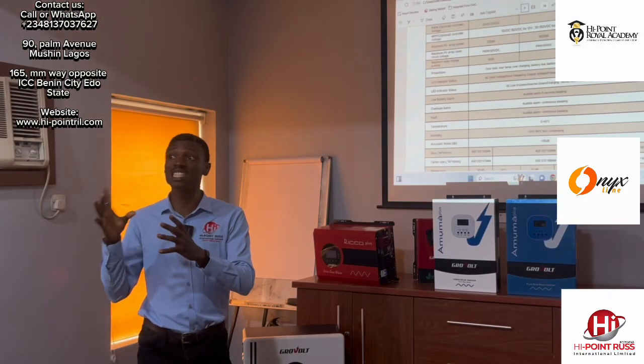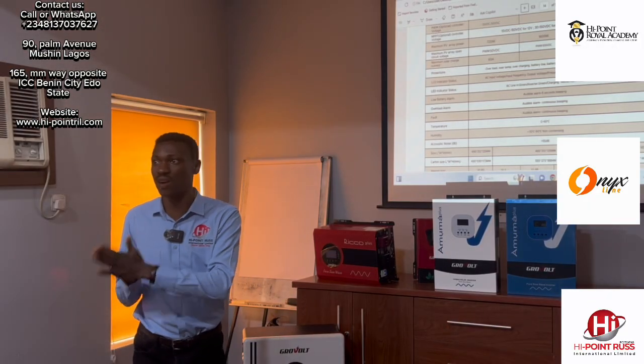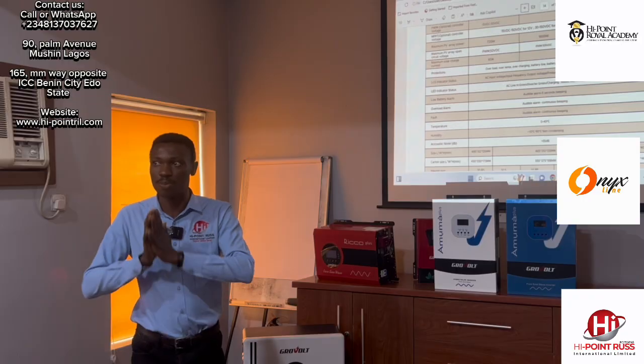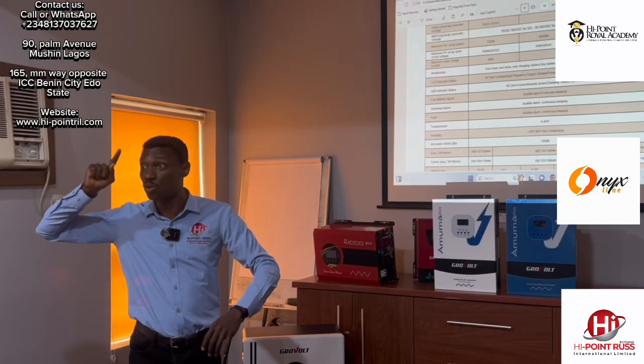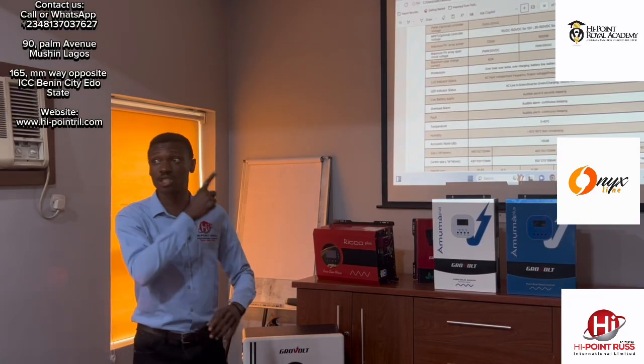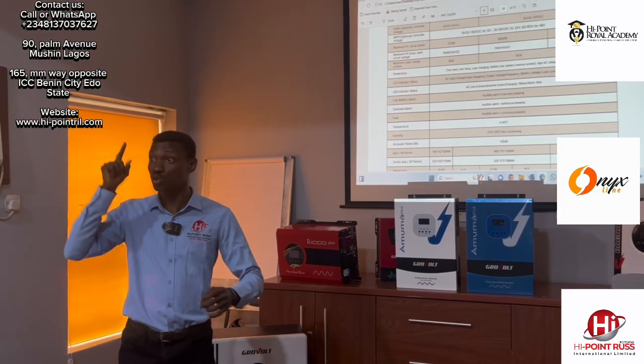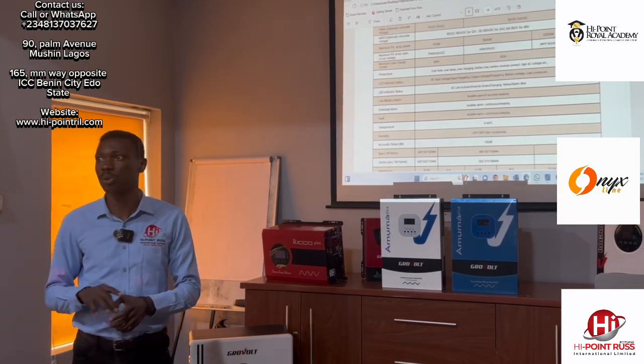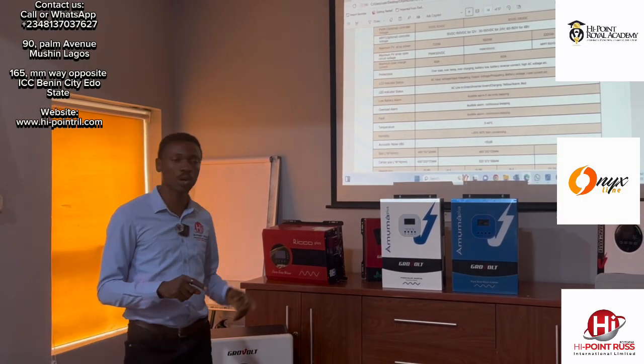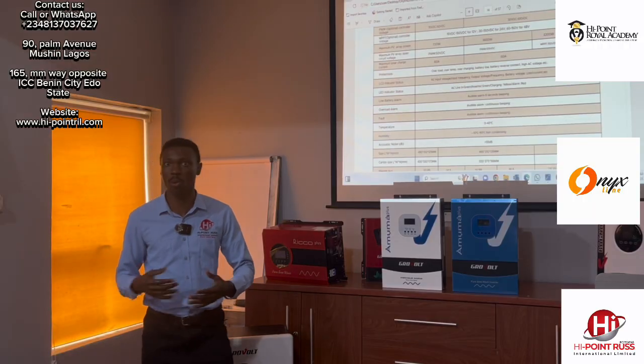The main fear with that lithium was always that if the battery drains too far, how to charge it back up. Even solar sometimes, only solar will not even charge that battery to come up. Many times I've seen that even solar alone will not charge that battery to come up. Do you understand? But with the lithium wake up function, it will boost, it will come up.